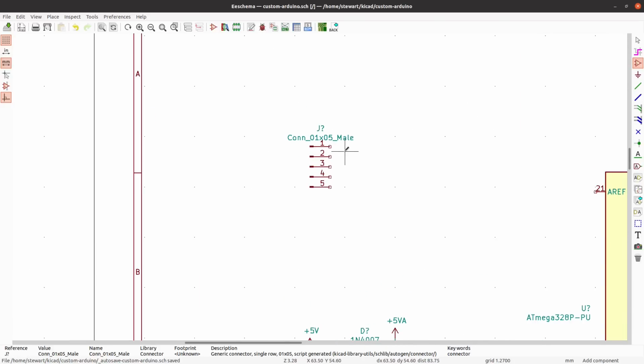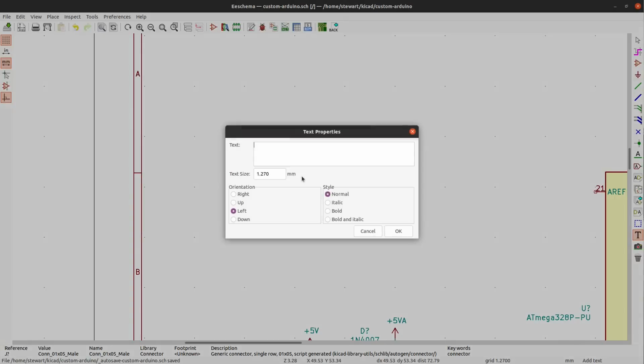So I'm going to use the same order as another circuit I've made previously. So the top one is going to go to the data ready. In fact, I'll write this in text next to here. So I've just clicked on the text button. I can put on here. The top one will be data ready. Then the next pin will be the transmit from the UART, which actually goes to the receive of the ATmega328. Then the receive of the UART, which goes to the transmit of the ATmega.